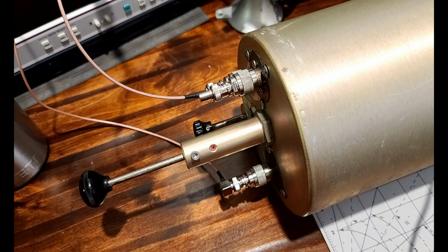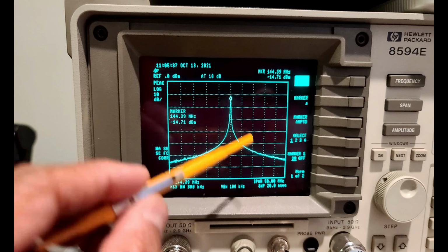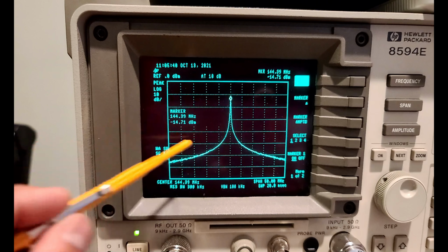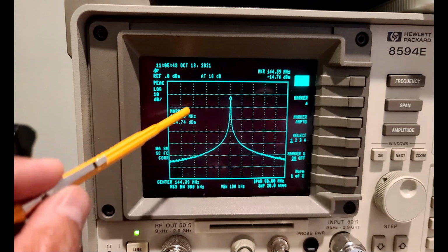Okay, so what I have here is I set up my center frequency to 144.39. We have a 500 kilohertz span. So let me turn on my tracking generator. So let me actually step back a little bit just so you can appreciate what we are seeing here. I'm going to switch it to 50 megahertz for now. At the outset, you can tell that we are right on the nail with the 144.39, and the marker is showing 144.39 in here, which is great.